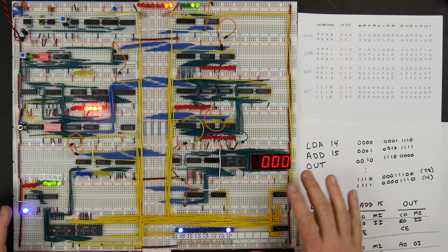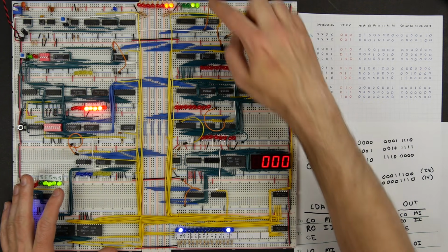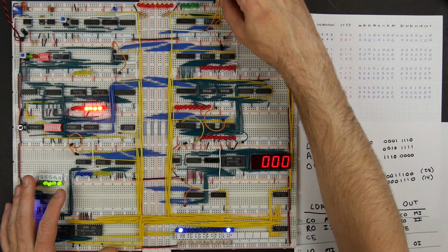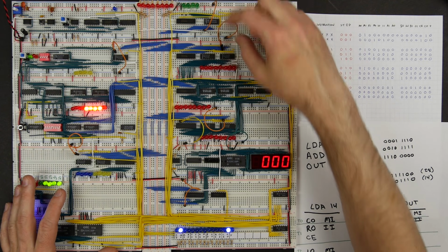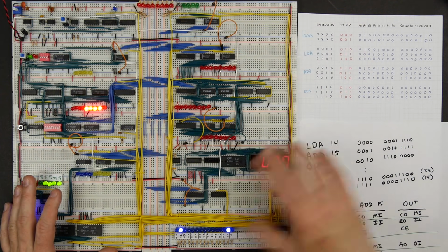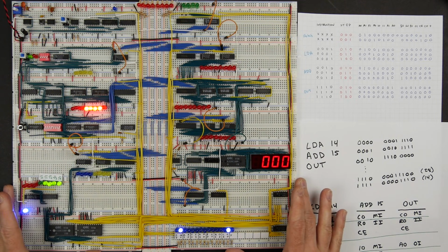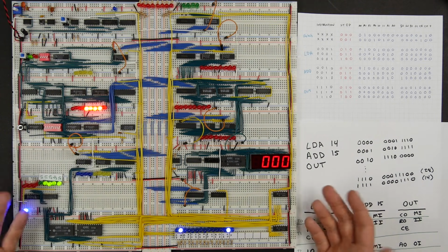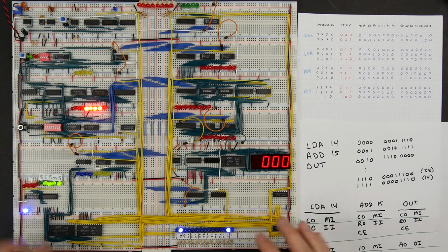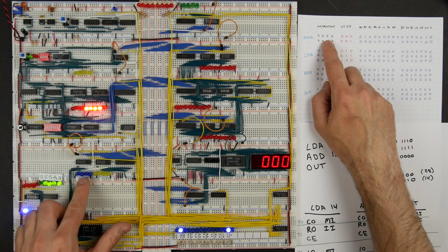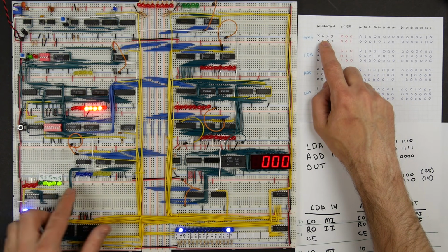First thing I'll do is reset everything. You see our program counter is at this weird value, but I can just reset that. And then our A register and B register are all 0. Everything else seems to be all 0. We're on T0 here. So I think we're ready to run the program, but I'm going to single step through just to make sure that everything is working the way that we hope it would. We're at time T0 here, so step 0, and it doesn't matter what our instruction is. In this case, it's all zeros, but that's fine.